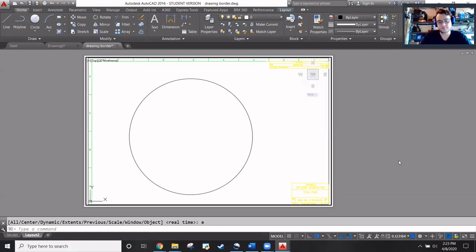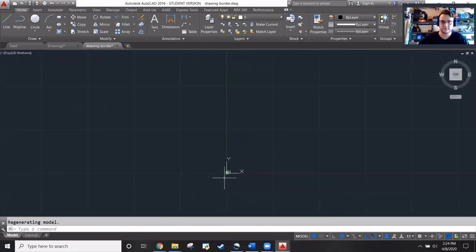And so that's the other super useful thing about zoom extents: if you somehow accidentally added content to your drawing that's way outside, like you were copy pasting, moving stuff around, and you got some rogue content somewhere, when you do a zoom extents, it'll zoom way out and you'll know, okay, I got to hunt down that crap and delete it out of my drawing, right? And you'll actually know it's somewhere on the border, right? Because here, I'll just show you.